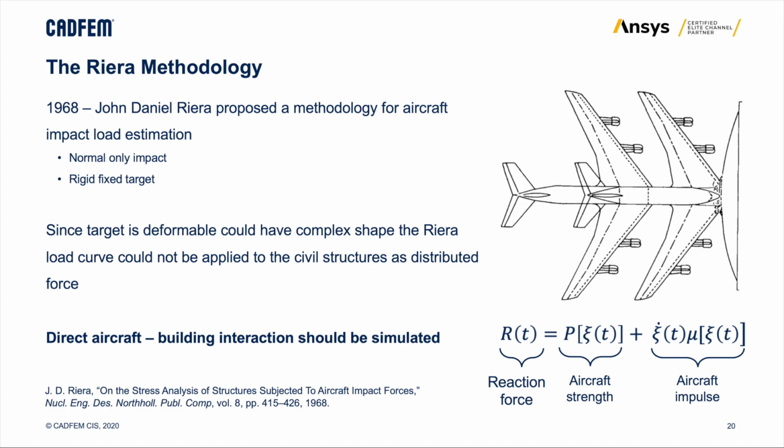The Riera methodology is widely used to simulate this type of loading. Riera assumed that the aircraft could be simulated as a plastic rod which impacts a rigid, fixed, flat target that cannot move, and the impact is a normal impact. Then the reaction force from the impact is assumed to be a sum of aircraft strength and aircraft impulse.